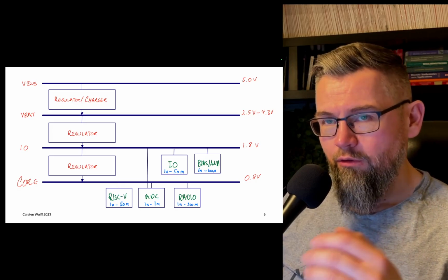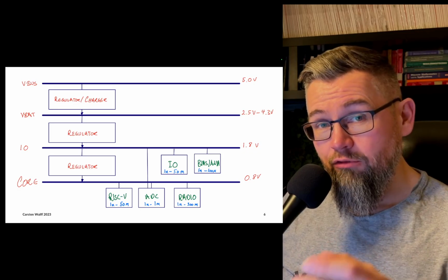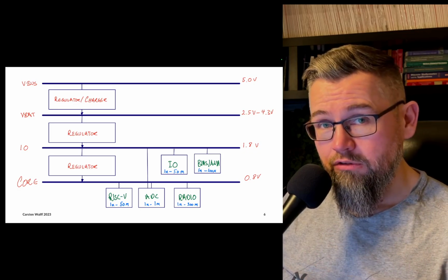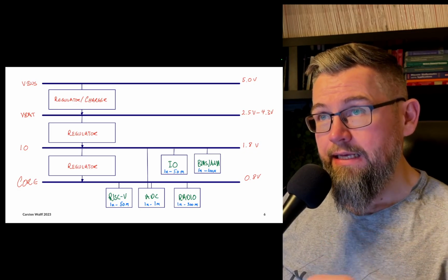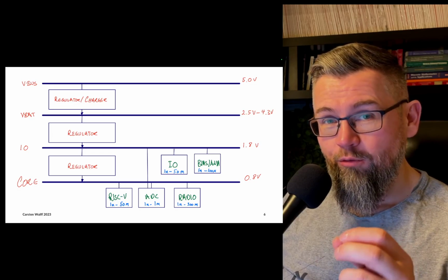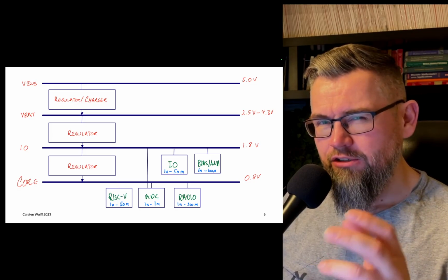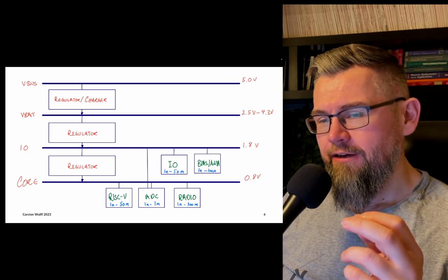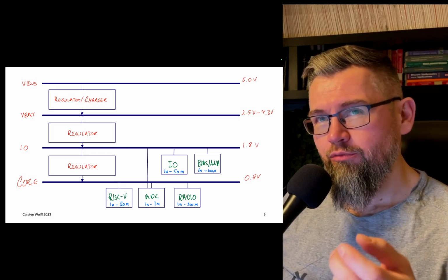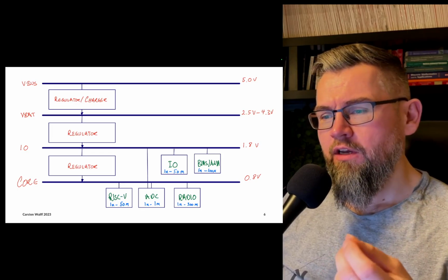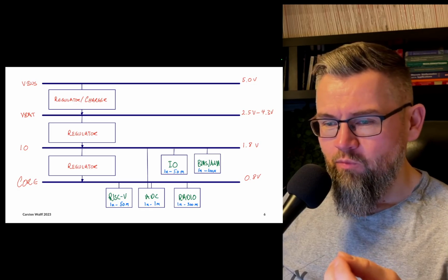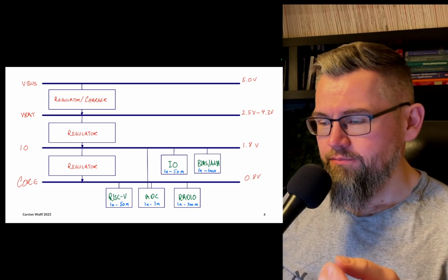So reducing voltage on digital cells, if they can run at that voltage at that certain speed, is always best. So there's a sort of power optimum: the lowest voltage you can run at the speed that you want is going to give you an optimum power point.